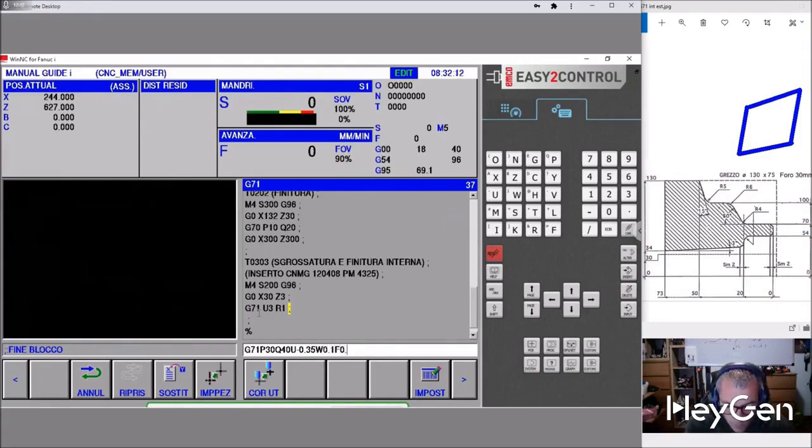Now I'm inserting, so I'm positioning myself at N30 X54. I need to do a 2mm chamfer to the edge of the part, so X60 Z0. Let's also set Z3 here, for safety, just to be sure.